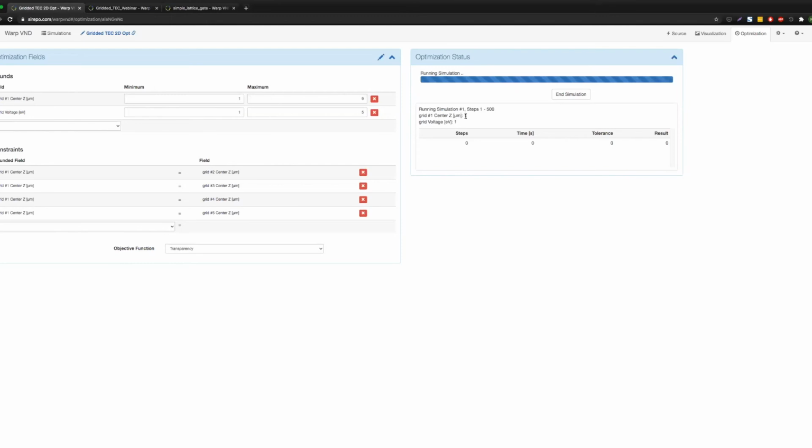And so this optimizer is designed to use a simplex type method, but it's been modified to first check the bounds. So it's going to check each one of the pairs of boundary conditions. So it'll check the low ends of the bounds, the upper ends of the bounds, and then the cross parameters of the bounds first. So you know that the first few simulations will be checking those and aren't going to be actually doing significant amounts of optimization.